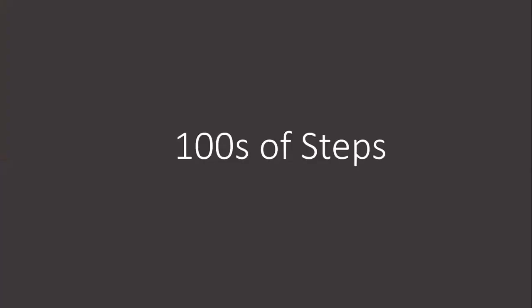So in actuality, there's hundreds of steps needed to achieve the building of a transistor or other devices. I just showed you kind of a simple mock-up, but the principle remains the same. We deposit thin layers of material, pattern it, and build on top of that until we get our 3D structure of the device we want.